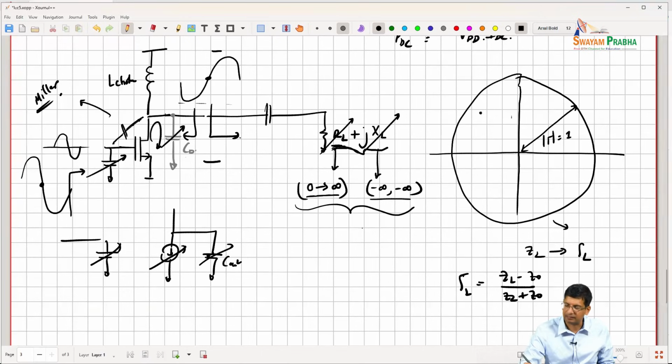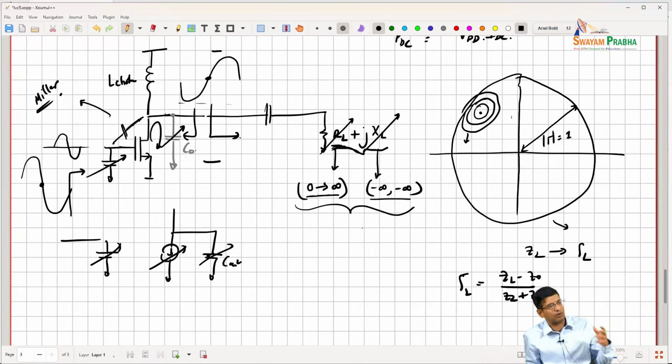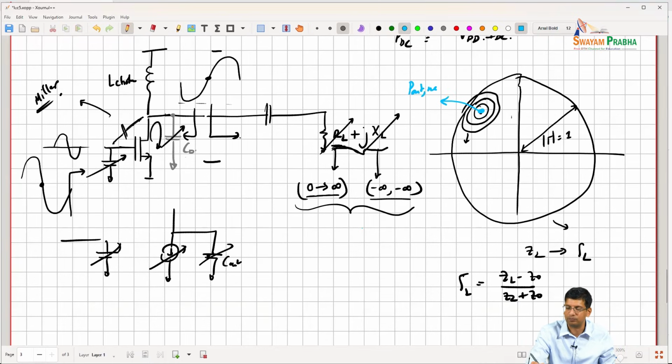And what we typically end up seeing is that the transistor wants to see something that is in this region, right? And you can plot circles of impedance, and there is a logical reason for it, considering constant resistance lines and constant reactance lines on the Smith chart. There's a logical reason for it, we can derive it. But effectively, what you start seeing is output power circles, where what this is saying is that at this point here, if I'm able to present this load, then I get the best output power that I can get, right? And I can optimize either the